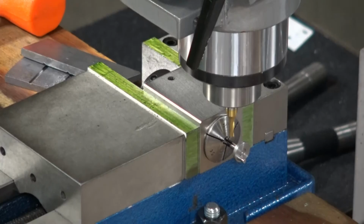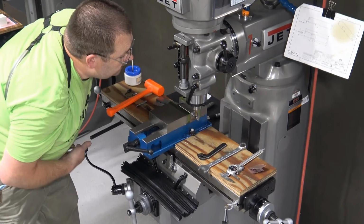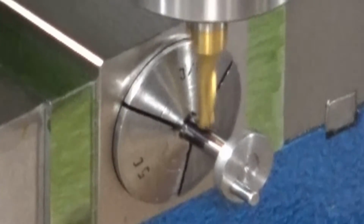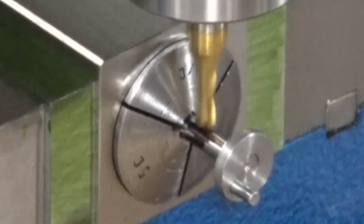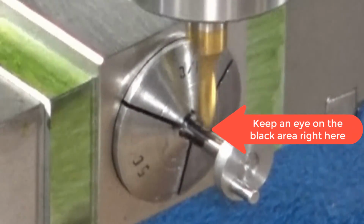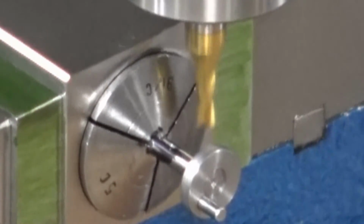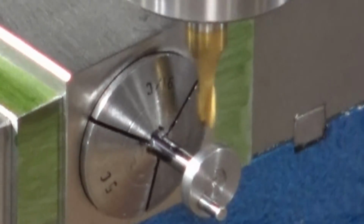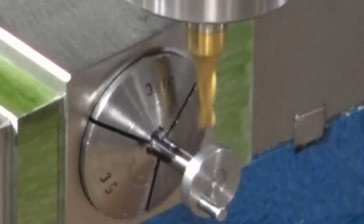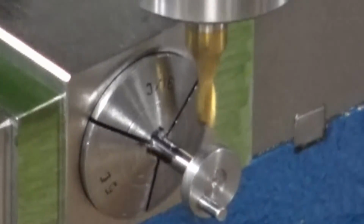Okay? So now that we're at that RPM, before I put any cutting oil on it, I'm going to bring the Z-axis up, or the knee if you will, until it touches. You should be able to see some of that black Sharpie go away. Okay? Now I've got a nice shiny spot coming through. I'm going to set the dial on my knee to 0. Ultimately, I want to cut this groove 30 thousandths deep. Put a little cutting oil on it.